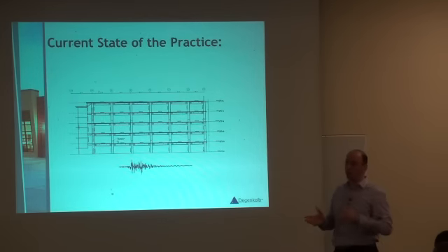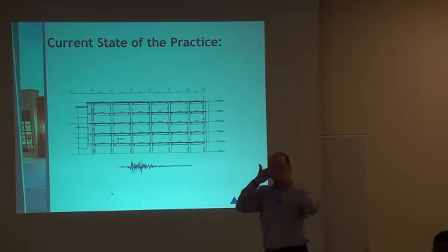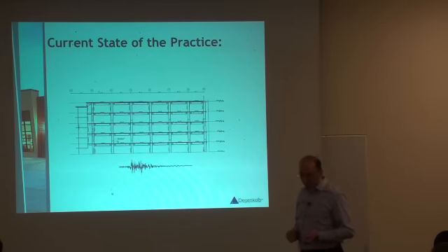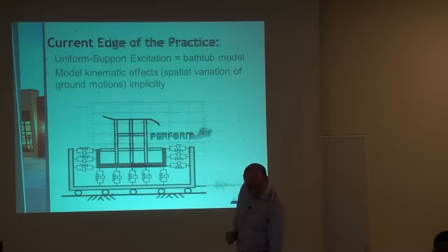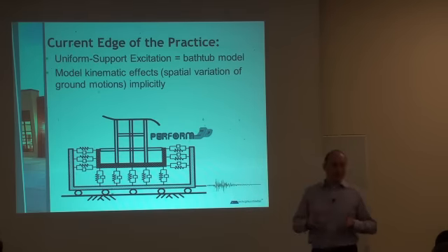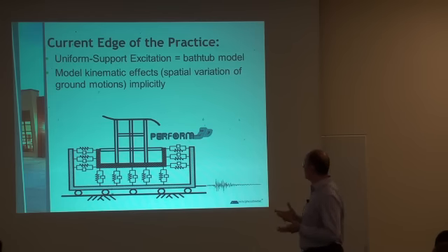For the most part, it's changing. But typically, people just ignore there's a basement, ignore there's any sort of interaction. You fix the building at the ground, and you apply the ground motions. We know that's not enough for many reasons. So companies who are at the edge right now in the industry use the so-called bathtub model, which